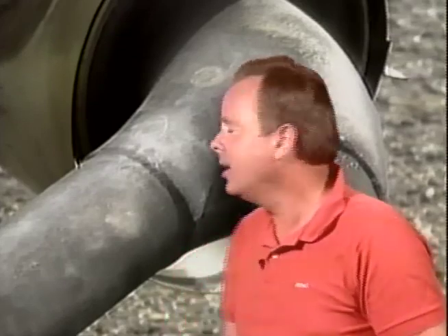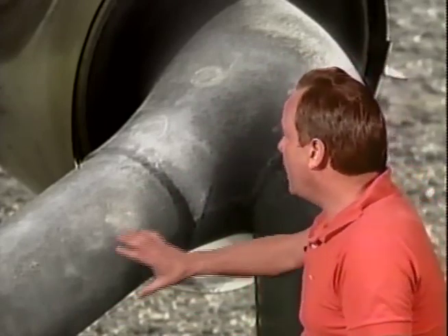All right, corrosion-resistant parts such as exhaust collectors should be blast cleaned using sand which has not been previously used on iron or steel. So if you're going to blast clean exhaust parts, use sand that has not been previously used on iron or steel. Why? Well, sand which has been used on iron or steel might have little particles of metal trapped in it, and these particles can become embedded in the parent material, that's this metal right here, and alter its corrosion-resistant qualities.